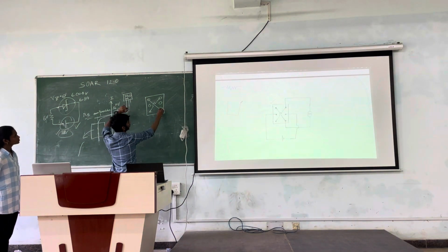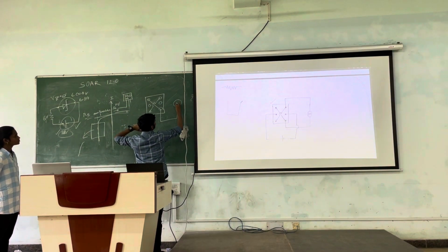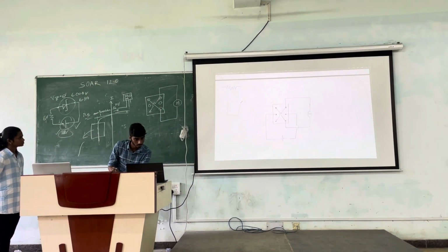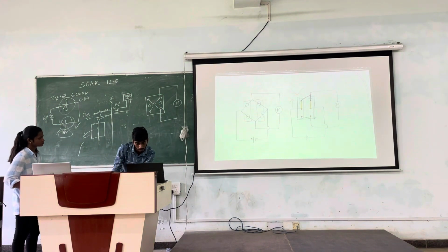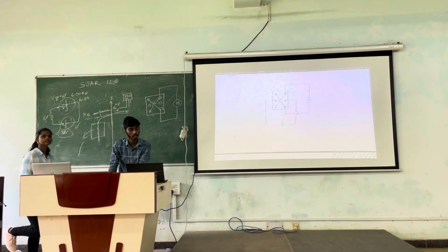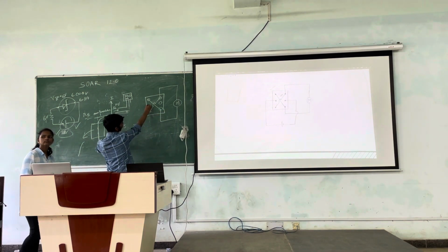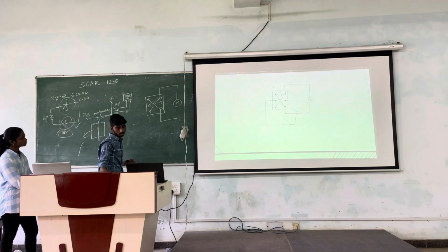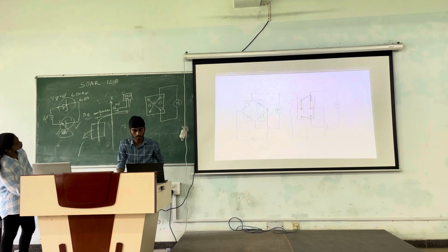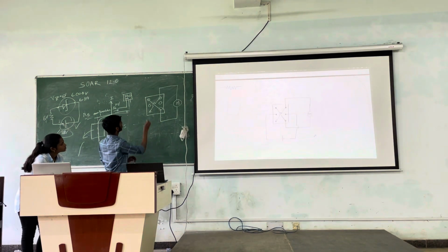Like we are connecting the motor here. As we already had this configuration earlier, we were connecting the motor to this terminal and this terminal. So we have the same configuration, just with these diagonal connections first. Now we are connecting the battery, just the same as we had seen here. We were connecting the battery to these middle terminals, so we are connecting the battery to them.